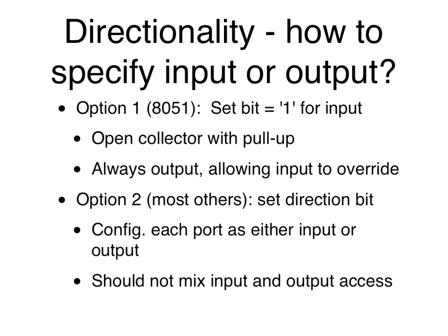Then there's option 2, which many other microcontrollers do, including the CC2540 extension: you have a way to set the direction of your port. You would write some values to a special function register to say if you want to do input or output. That's what I call option 2.